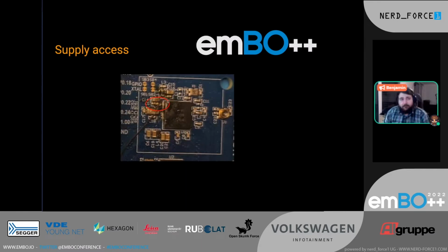So then you need to find it on the circuit board. How you do it, well, depends. If you get lucky, it is clearly marked, like it's marked capacitor 5 on both the schematic and on the board. Maybe you need to do some reversing, usually using your meter in continuity mode, because you know that one side of the capacitor will be a dead short to ground because it is connected to ground, and the other side will not be connected to ground because it is connected to the decoupling pin.